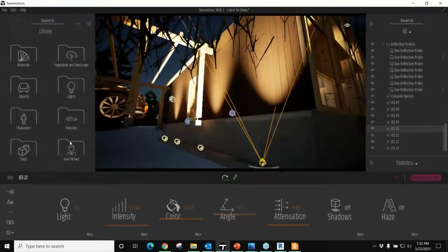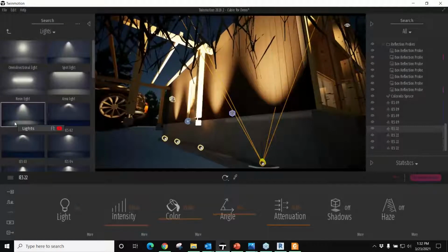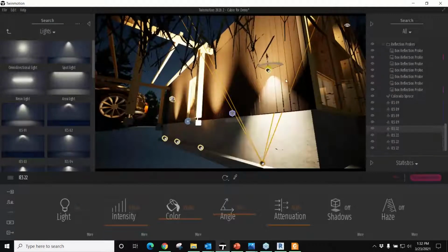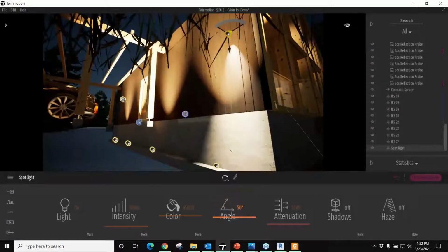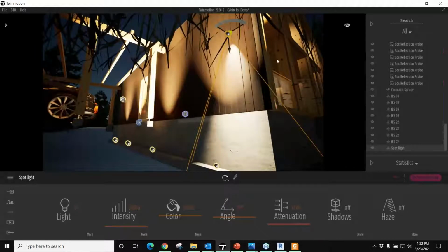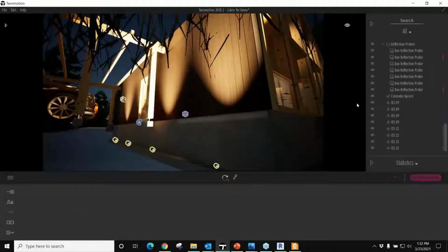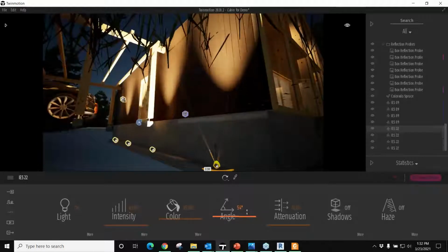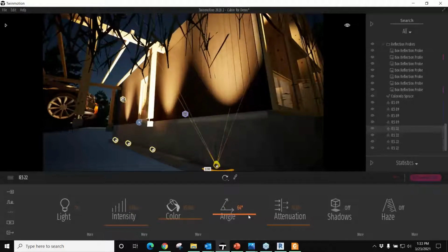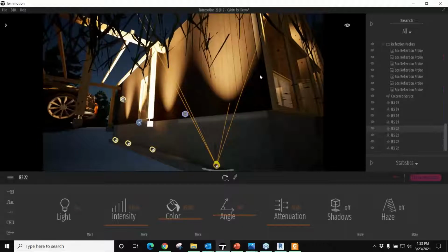So lights can be found from our content library, and essentially you just drag and drop them into the scene to place them, and then you can control and adjust them however you want. So pretty easy there. And the other lights you might have noticed, for those of you that have ever worked in 3ds Max, I made these instance copies. So as I changed the properties of one light, it's changing all of my instance copies at the same time. So kind of a shortcut there for controlling down lighting, up lighting, interior lighting. So that's basically it with the lighting.